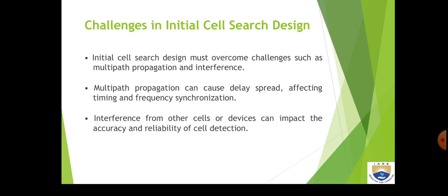Challenges in initial cell search design. Initial cell search design must overcome challenges such as multipath propagation and interference. Multipath propagation can cause delay spread, affecting timing and frequency synchronization. Interference from other cells or devices can impact accurate and reliable cell detection.